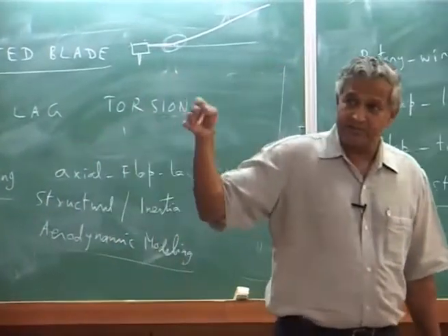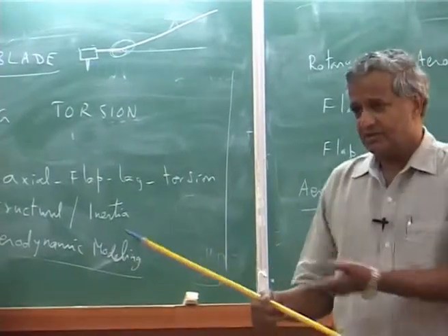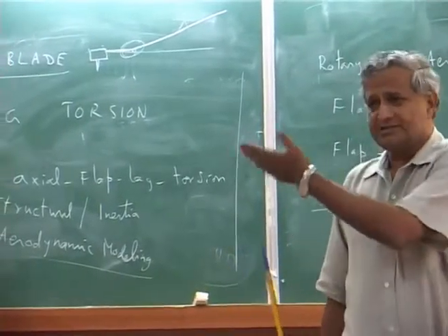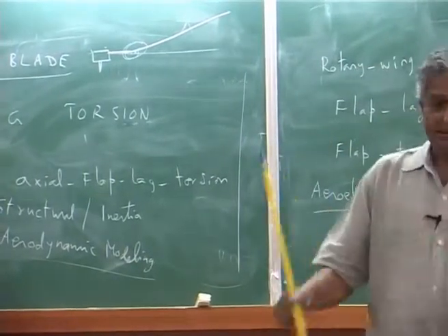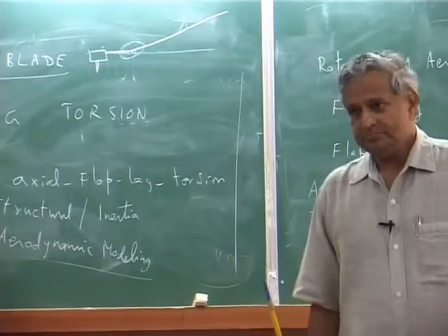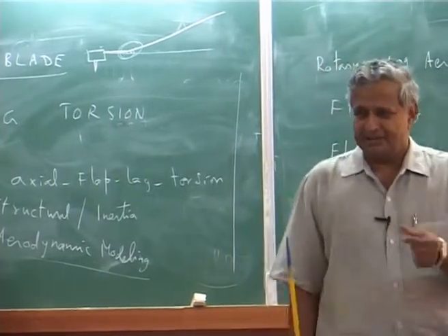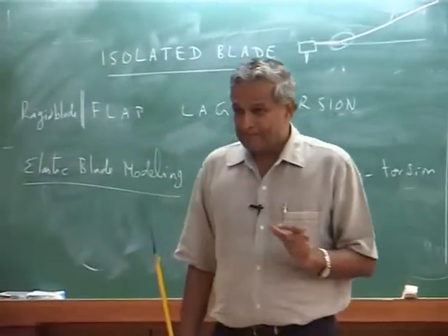You have to make a measurement. You put a strain gauge there and make a measurement, because that test I told you, they measured at 50%, 55%, something like that. Bending moment at 50%, and then try to correlate how your theoretical value matches with the flight test. But number wise, I don't see your question really.